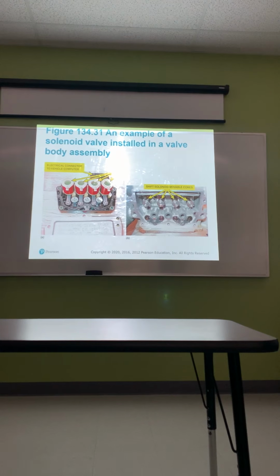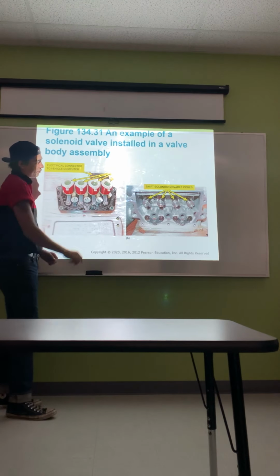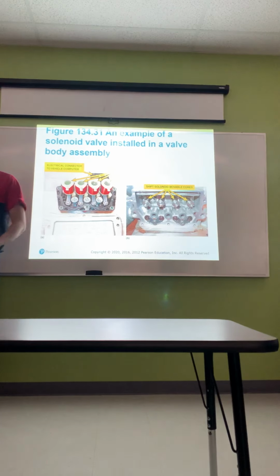An example of a solenoid valve installed in a valve body assembly. So we actually have each one of these solenoids activate when power is getting sent through, which then sends the fluid through to another portion of the transmission, causing it to shift.